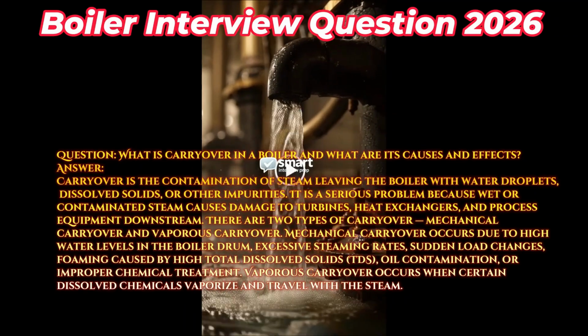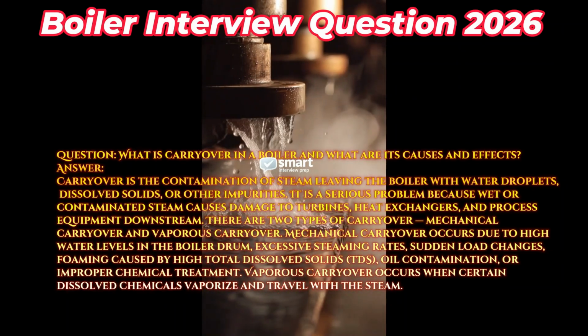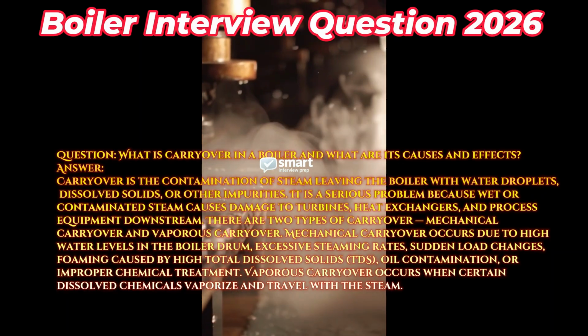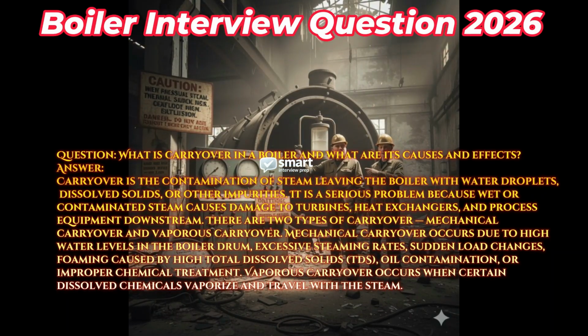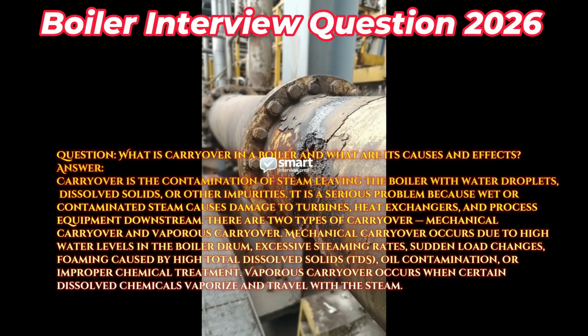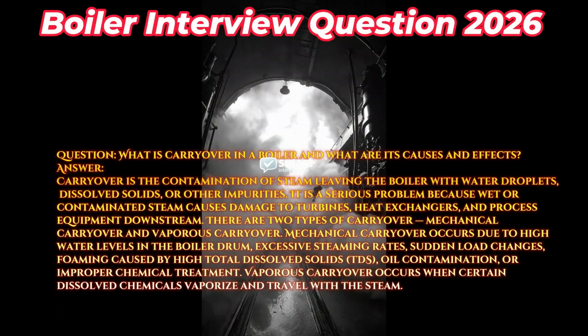Answer. Carryover is the contamination of steam leaving the boiler with water droplets, dissolved solids, or other impurities. It is a serious problem because wet or contaminated steam causes damage to turbines, heat exchangers, and process equipment downstream. There are two types of carryover: mechanical carryover and vaporous carryover.